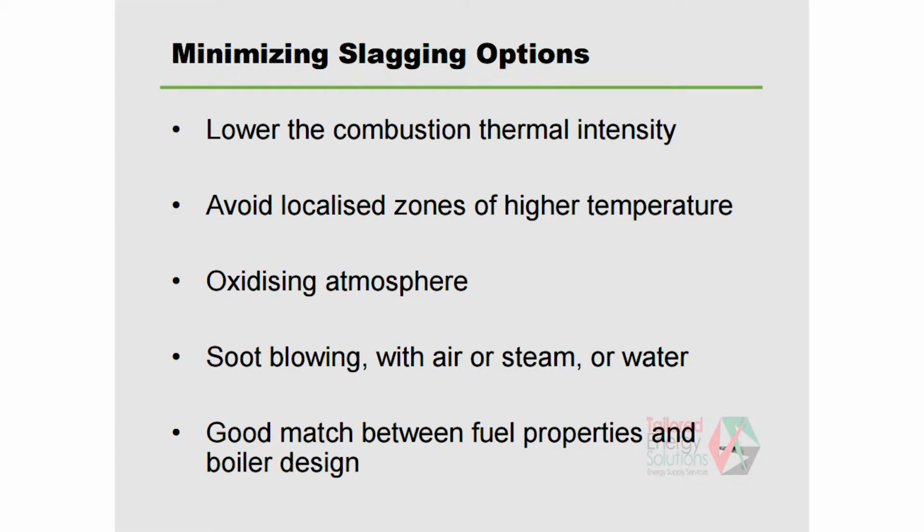It's better to create an oxidized condition, because in oxidized conditions iron tends to be iron 3+ rather than 2+. The iron 2+ oxide has a melting point about 100 degrees lower than iron 3+. That's why we want to have decent excess air here.